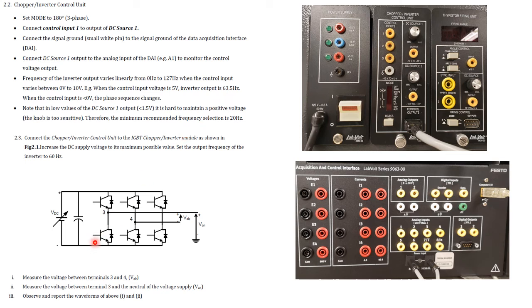So what you should do for this lab, you should connect the DC variable voltage that I showed before to points 1 and 2 of the inverter. Then you should build this circuit, which is already built. Then you should measure the line to line voltage, let's say E1 or E2, between 3 and 4 using VAB, and between 3 and ground.